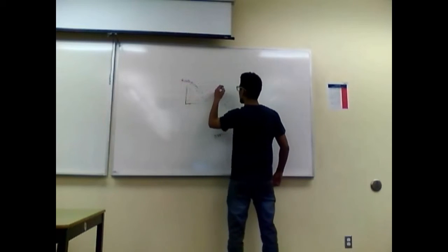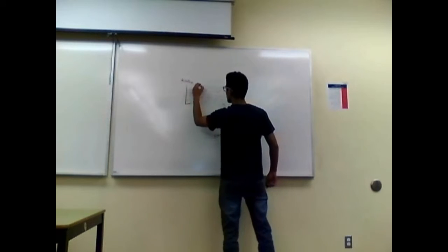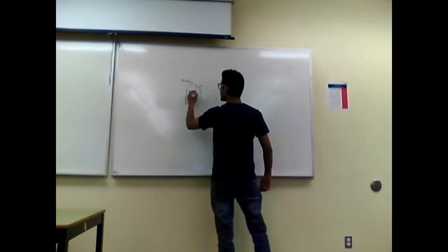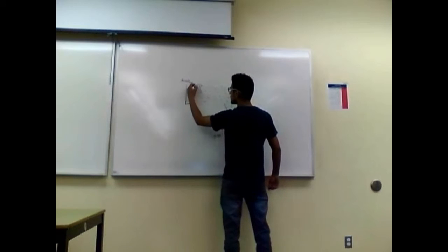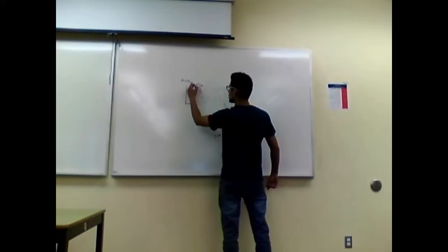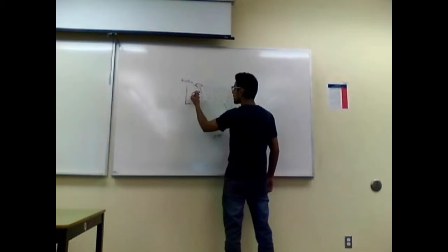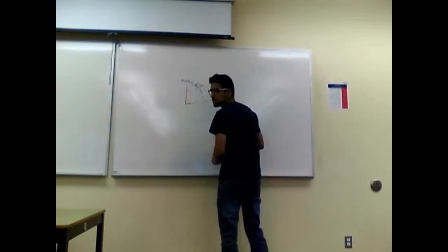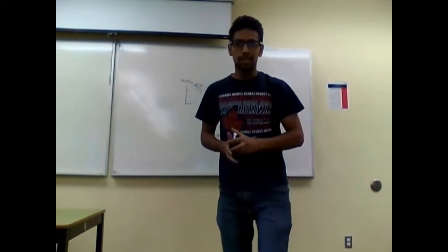The next step is to spread the particles on the surface, usually at the crack. So when the electricity starts flowing, it creates a flux on the surface, mainly on the crack, which helps to detect this crack. So this is the major mechanism of magnetic particle testing. We have other techniques also. The next one is